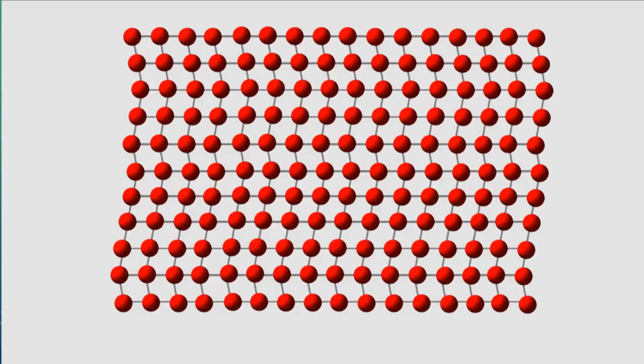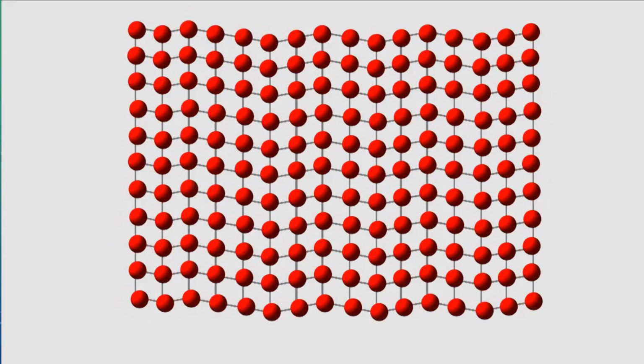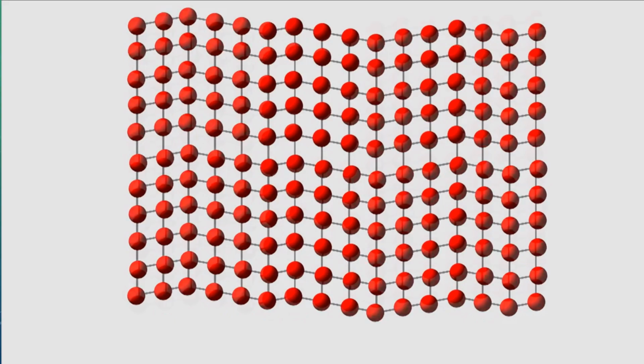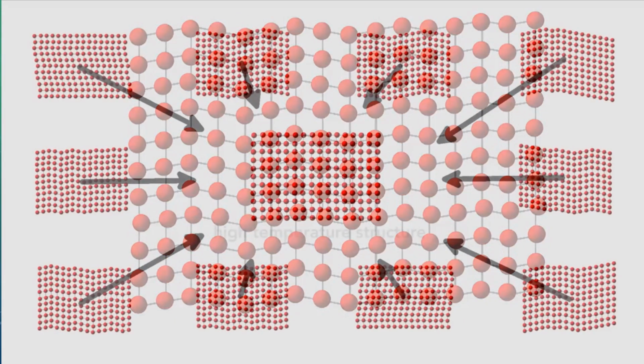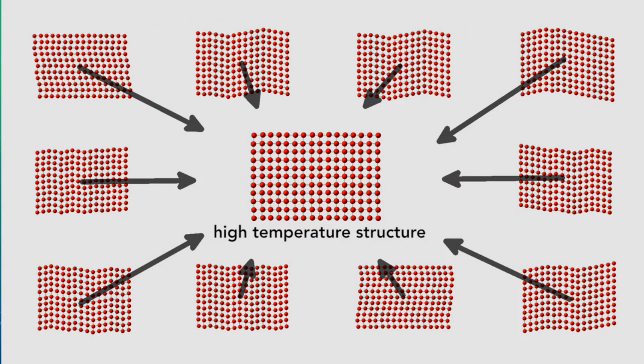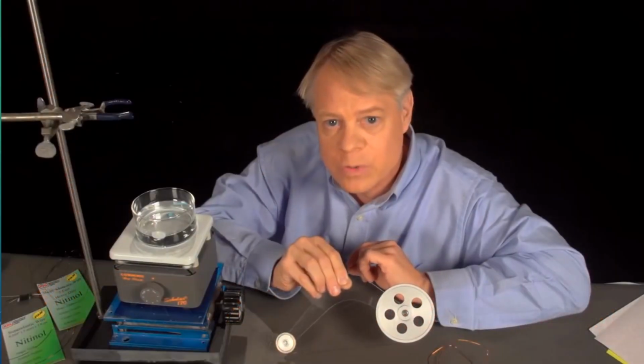They can slip, where atoms can rearrange quite a bit more. So when the temperature is raised again, these rhombuses, no matter how they are distributed, return to tidy squares. The only structure that can result is the original structure, and so the nitinol reverts to the shape it had at high temperature. There are some clever uses for nitinol.